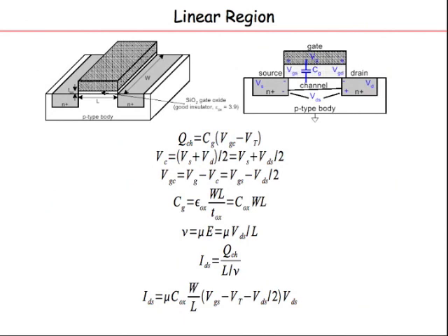On the positive side, when I reduce the size of the transistor, I reduce the currents and I reduce the power. So smaller size is good for area and power, but not good for speed. So there is a trade-off out here. That is typically what happens when you do engineering. You have these trade-offs. It's very difficult, because if you try to squeeze one, the other side blows up. So you have to find an optimum across all this.